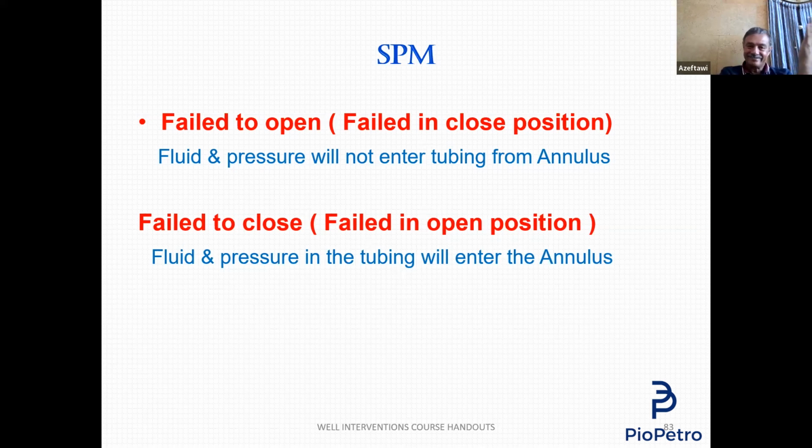Wireline, in general, whatever it is, a slick line or braided line or electric line, when we run it in the hole, we run with gravity. But that's why when we start having very high deviated wells and horizontal wells, you cannot use a wireline and slick line because there's no gravity, horizontal section and heavy.